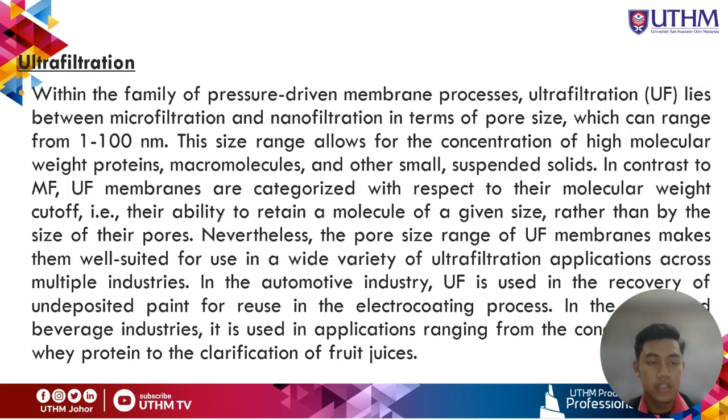For ultrafiltration, within the family of pressure-driven membrane processes, ultrafiltration lies between microfiltration and nanofiltration in terms of pore size, which can range from 1 to 100 nanometers. This size range allows for the concentration of high molecular weight proteins, macromolecules, and other small suspended solids.